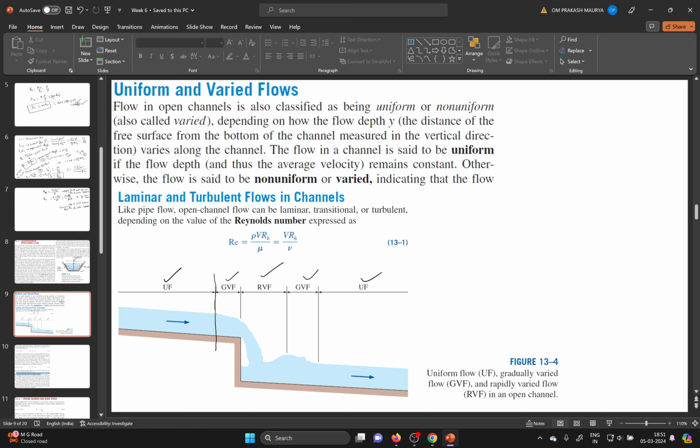If you look here clearly, the depth of the flow is a little bit lower, very slowly, but after that the depth reduces very fast, in a short length. Then the velocity goes down, and after that it will gain uniform flow. So rapidly varied flow is a short phenomenon, not for a long reach. After that the water flow will always try to gain uniform flow. Rapidly varied flow is nothing but a very small reach, a very small length, where your depth varies rapidly.